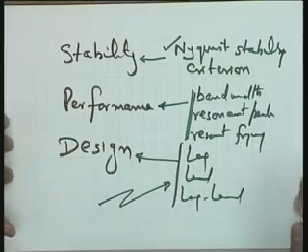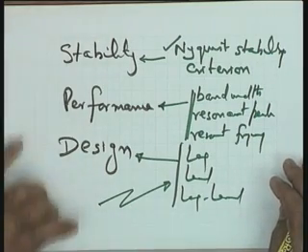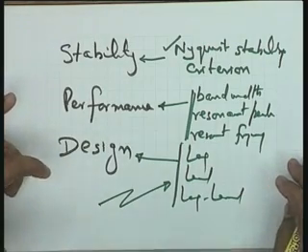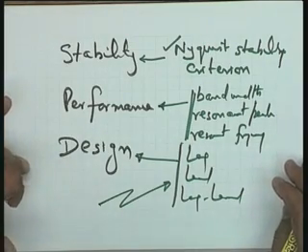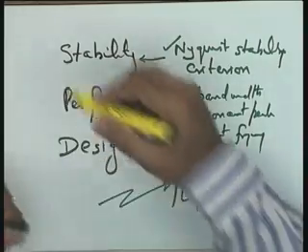But you will find that when you go to the frequency domain, the trial and error, though there, is reduced considerably. All those questions which you had been raising to me will get reduced when we go for the lag compensator, lead compensator, or lag-lead compensator in the frequency domain. Okay? So, these are the basic features of the frequency domain design analogous to the root locus design which we are going to take up, and therefore, without spending more time, I get started with the first feature, the Nyquist stability criterion.